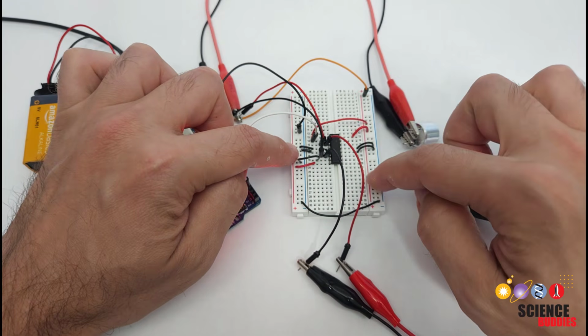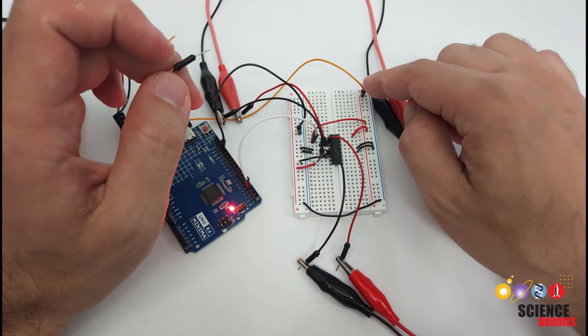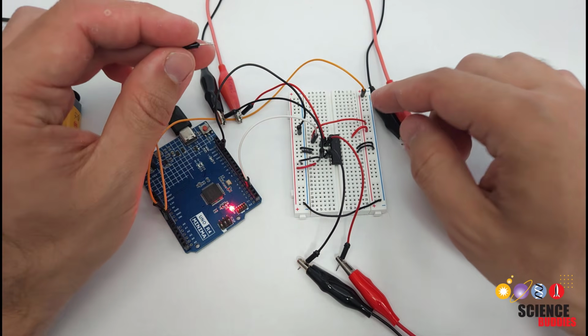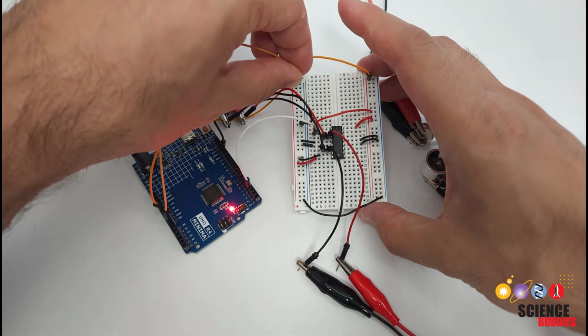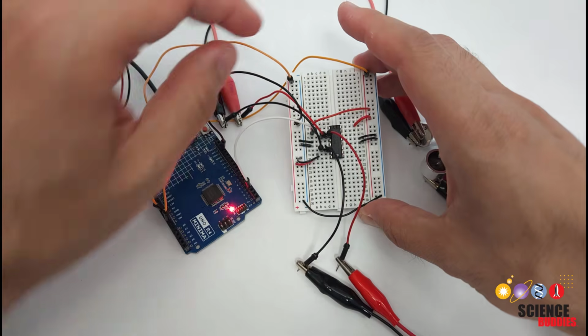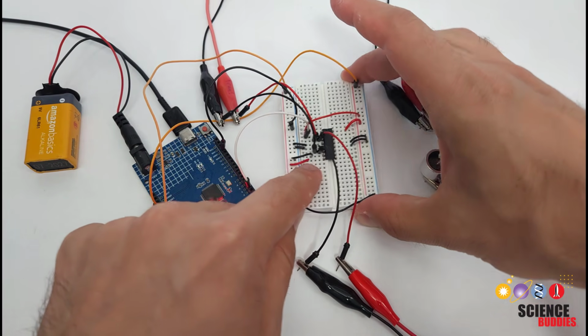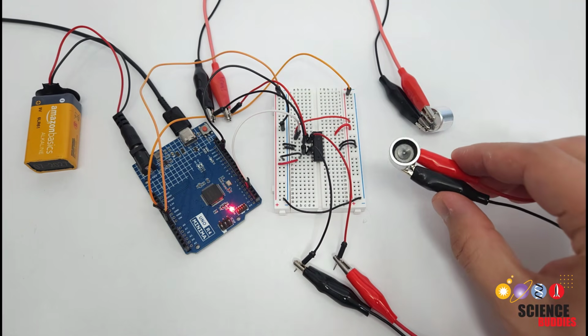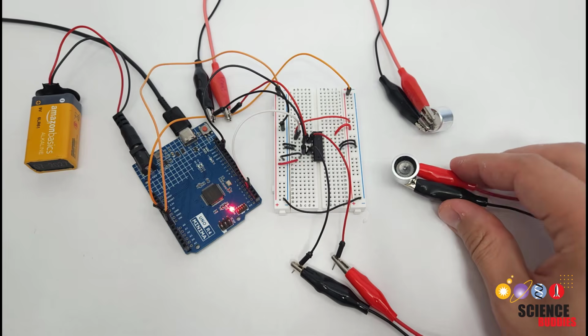I did not connect that over to the power bus on the right side, which is connected to my Arduino's 5 volts, because I don't want to short circuit those together. So I'm going to plug this jumper wire into the power bus on the left side, and then thanks to this little red jumper wire here, that is now powering my H-bridge, which is going to power my transmitters with 9 volts instead of 5 volts.